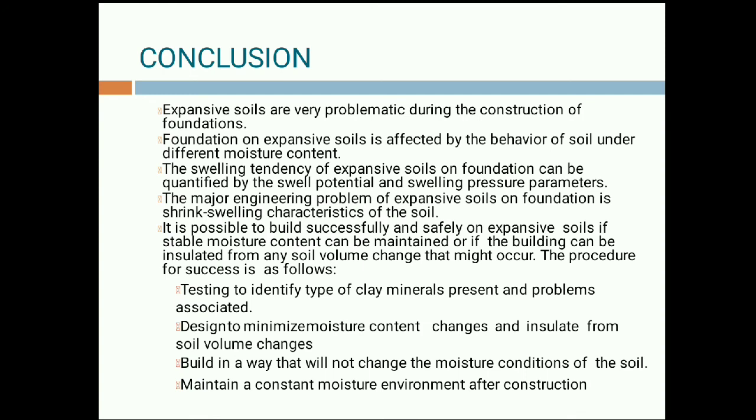The procedure for such success is as follows. If we restrict moisture entry inside the boundary of the building, or use vertical moisture barriers, or restrict the change in the moisture content of the expansive soil, we can safeguard our structure.